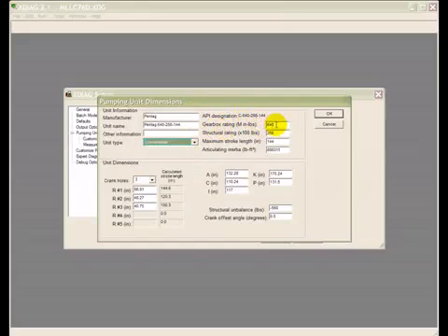And you need to put in your gearbox rating, structural rating, maximum stroke length, and also the dimensions of the unit. For the articulating inertia, if you don't know what that is, you can simply copy what the program shows for a Lufkin unit, for example. You can see this number, by the way, when you're in Rodstar and you include speed variation. This number actually doesn't make any difference in XDIAG, so you can put in 0 for this number.